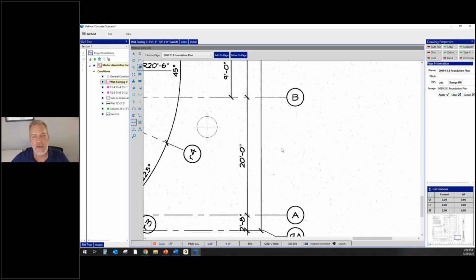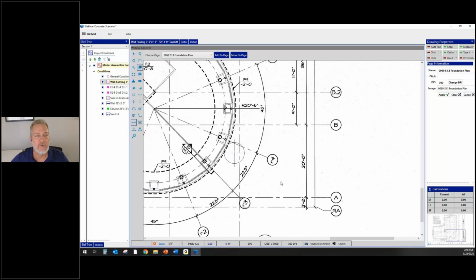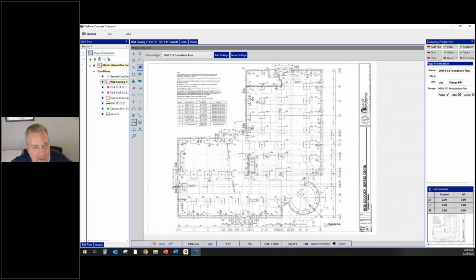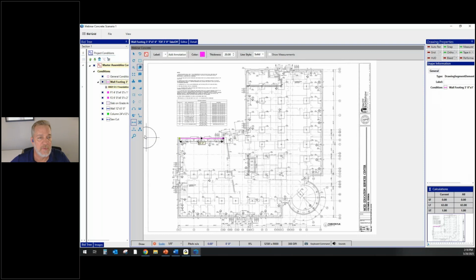All right, so let's zoom back out. We're zooming in and out using our mouse. If you've ever used any takeoff programs like some of the other ones that are takeoff only, you can measure in segments, which means you're measuring from point A to point B, and then the next point A to point B, or you can measure in a continuous length, which I'm going to do right now. I'm not going to be perfect on this for the sake of demonstration, but I do want to show you some things that the Edge will do that's kind of unique.